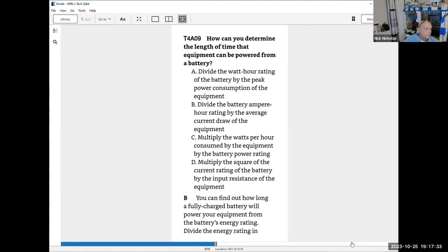Not all batteries can deliver maximum draw, but in theory, you could draw that. And you could operate drawing a 100 amp load for an hour. But generally speaking, you're not going to do that, and batteries won't withstand that. That'll damage the battery. So remember that as a practical answer. This is the answer from the book, which is theoretical.